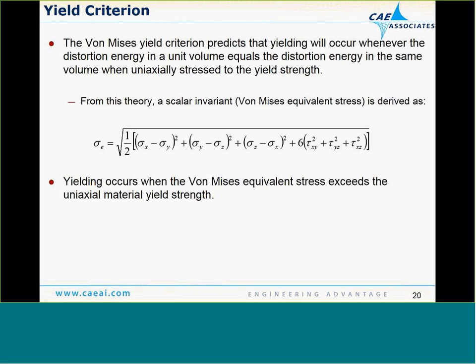So we divide those, or we perform that operation, to compute the stress quantity that we can compare back with our test data, and that's where we use the von Mises yield criterion, which is defined as such, the equation below, which is written in terms of components. You can also use principal directions, which is simply the square of the sum of the differences of the principal component stresses. And this was developed and finalized by our friend von Mises we just talked about a couple of minutes ago.